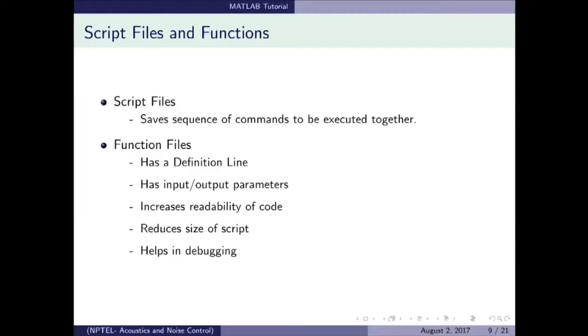Script files are simple .m files where we write and store a sequence of commands to be executed together. Instead of writing those commands in the command window, we save them in a script file so that we can have access to them whenever we need. We will look into a few script files already saved and some we will write now. In those script files, we will come across new functions and we will learn about them.